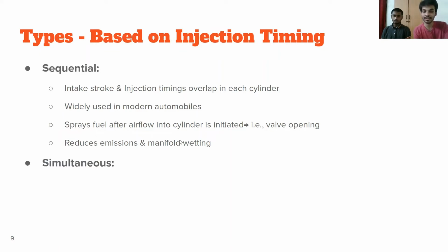Another type of MPFI system is the simultaneous one. In this, the fuel is injected into every cylinder at the same time. It has similar disadvantages as the batch type MPFI system.